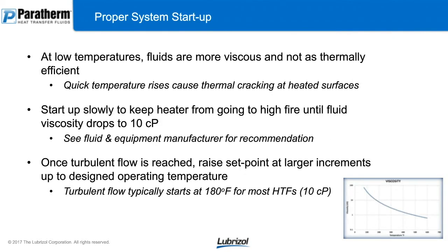Well, we talked about how low temperatures and higher viscosity fluids are not thermally efficient because they're not giving you the turbulent flow that you need. If you apply quick temperature rises, you will crack thermal fluid at the heated surface itself. So you need to be able to start up slowly to keep the heater from going into high fire until your fluid viscosity drops to around 10 centipoise. And that's just a rule of thumb. You really need to see your fluid and equipment manufacturer for this recommendation.